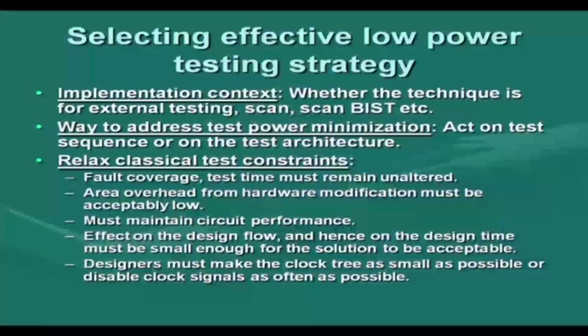Now, as a test engineer, we would like to have some relaxation in the classical test constraints like fault coverage and test time. Fault coverage, actually, nobody will accept a situation where fault coverage gets reduced. If some of the test patterns are consuming a lot of power, then possibly we can say that we do not apply those patterns.